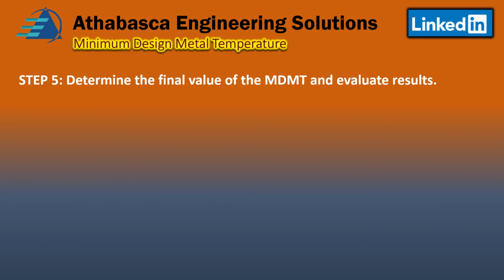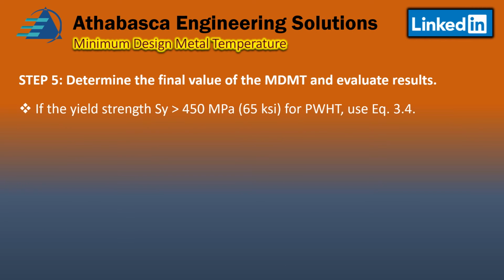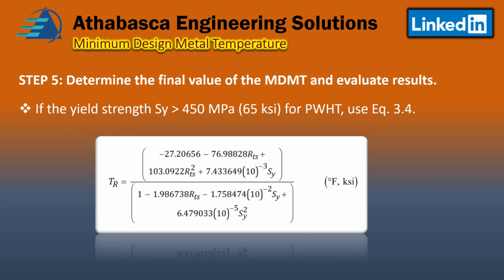So we're going to go on to a bit more detail. If the yield strength is greater than 450 megapascals or 65 ksi, for post-weld heat treatment, you can use the following equation. It's quite an involved equation. I believe ASME has examples, so you can test your formula to make sure it's accurate.